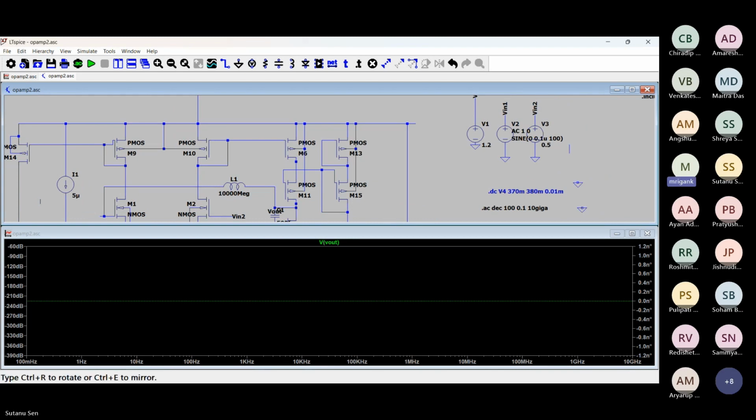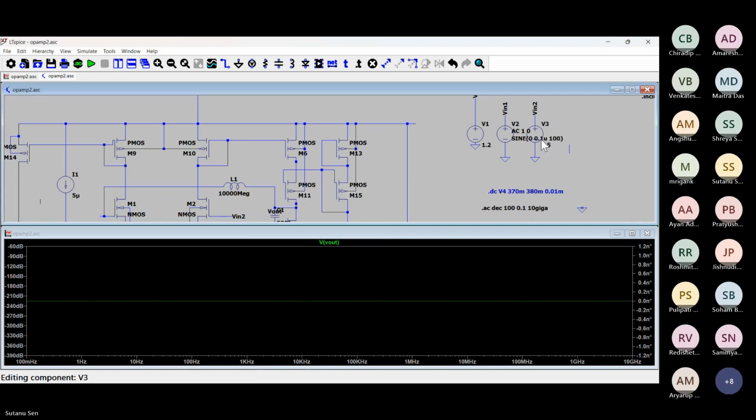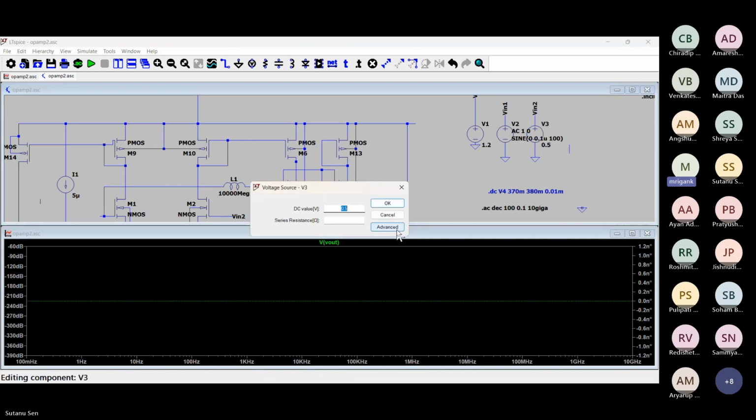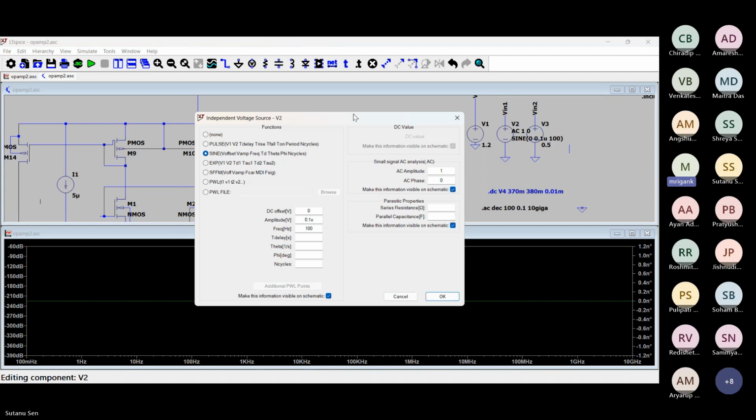What we are trying to do is put it in voltage follower configuration. As far as DC is concerned, for DC omega L is 0. So it is like a voltage follower for the DC. So whatever is the output voltage, it should automatically develop. It should be equal to the negative terminal voltage.